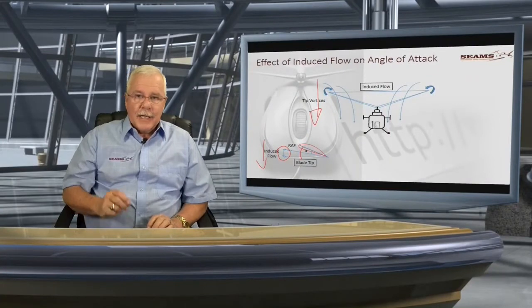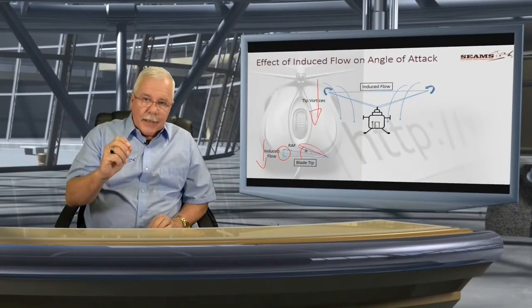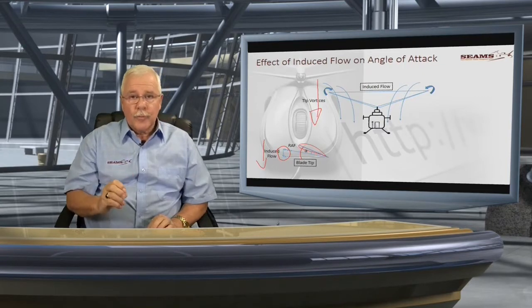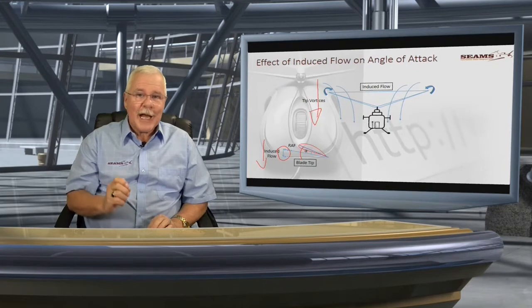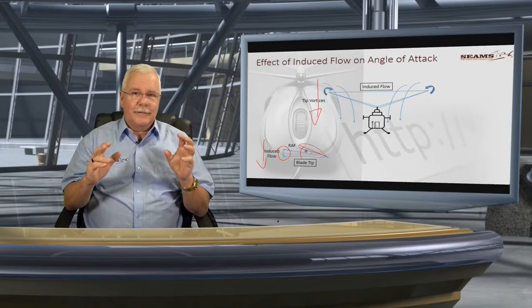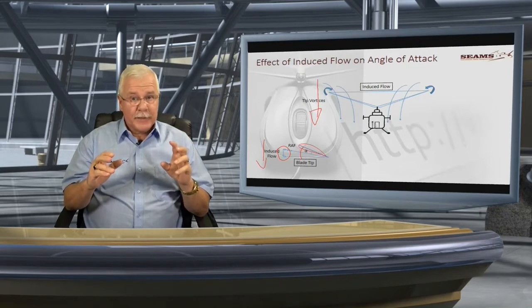Now, the rotor blades do not stall because of the blade angle. It stalls because of the angle of attack. And the average angle of attack for a blade to stall is around about 16 degrees.